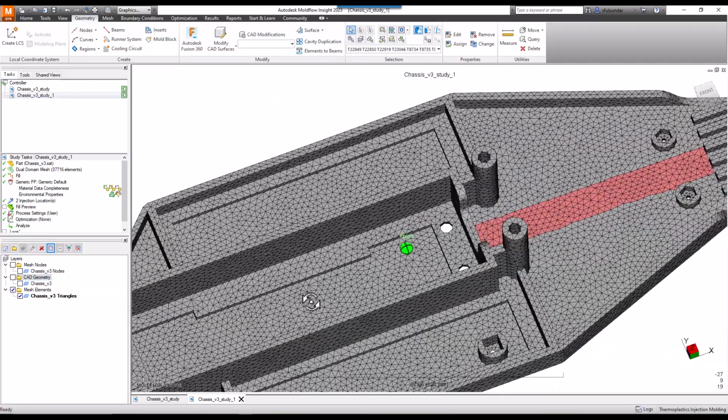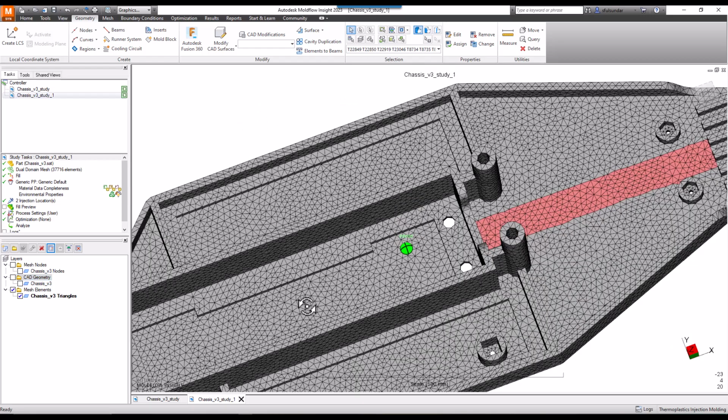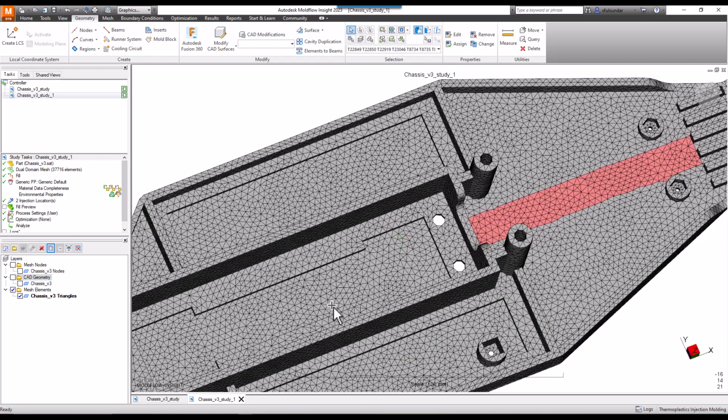I can say that if you face any challenge creating the flow leaders or deflectors and you want to select a set of elements which are not falling in line, you can split the face, come back, and your geometry, oh sorry, boundary conditions remain intact. Even if you model the feed systems or cooling channels, they remain intact. I hope this tip and workflow would be useful for optimizing your analysis as well as the geometry.